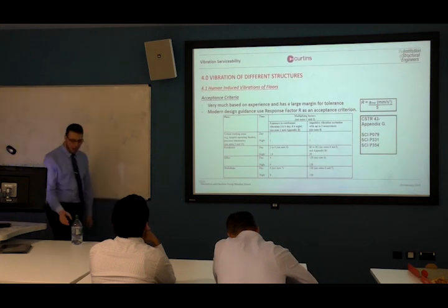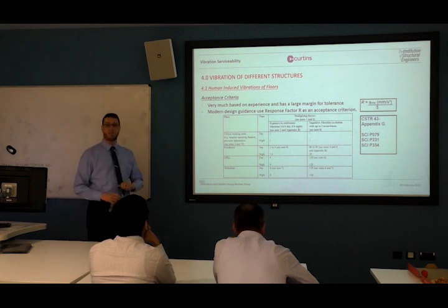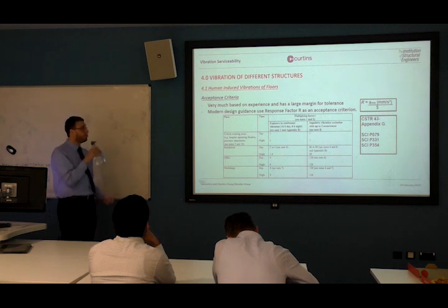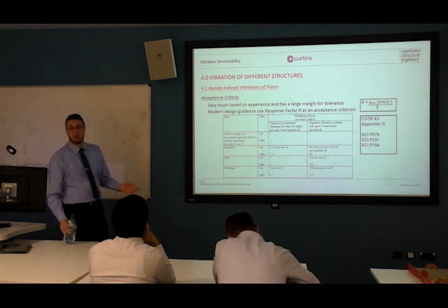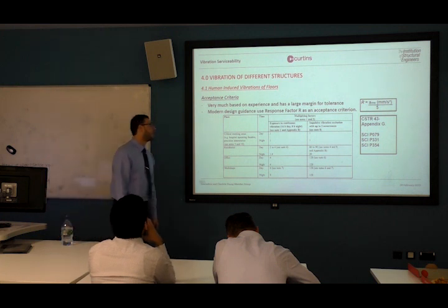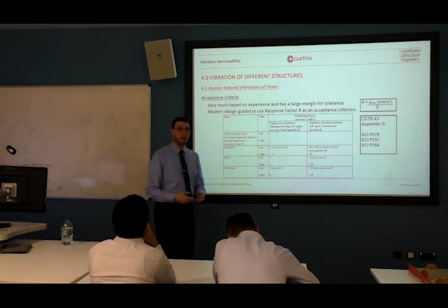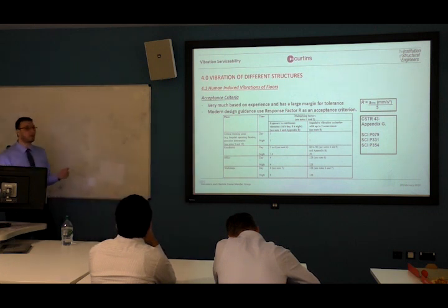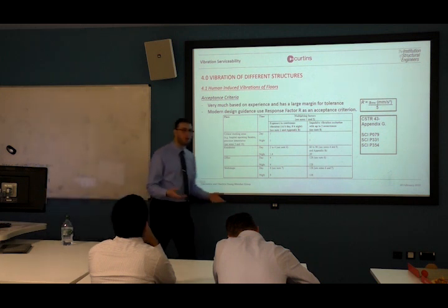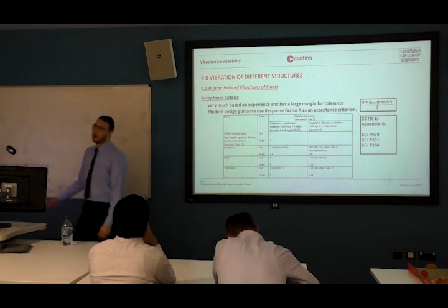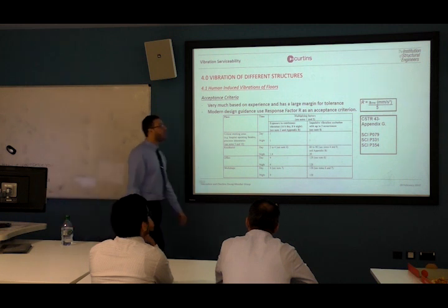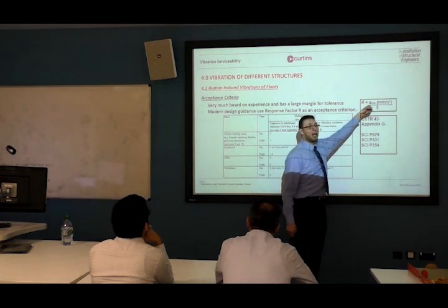Right. So how do we decide whether the vibration is acceptable or not? As we said, we check the response. Modern codes and guidance say we use something called response factor, R. You're all aware of it. I know in our offices, R is 8, it's too high. R is 10, it's not gonna work. R is 4, it's fine. No, what's R? R is actually what you get from the acceleration